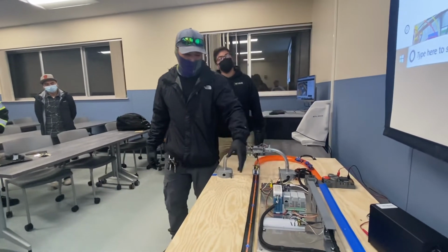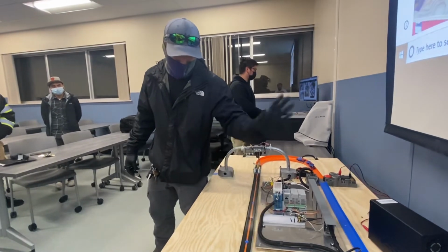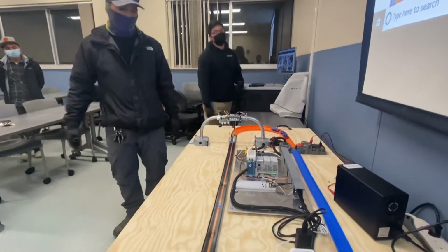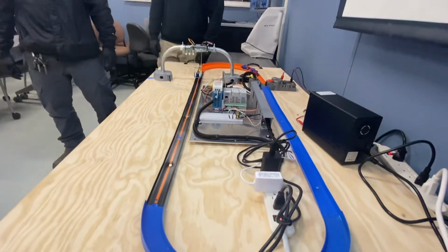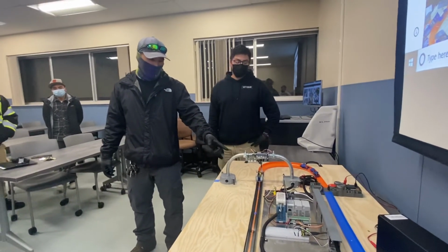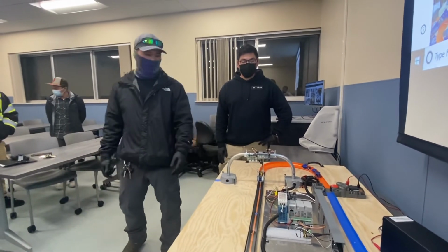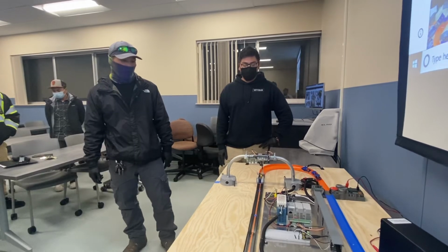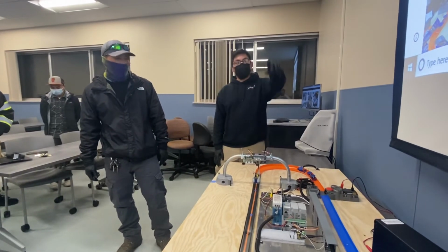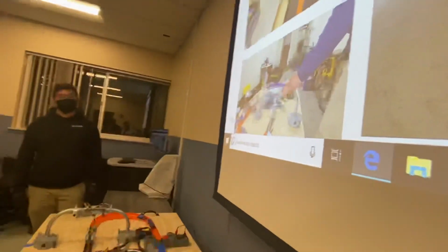as well. Especially with this one, we didn't want any power getting cut and severed and making contact with any other metal parts and causing any electrical hazards for us. Luckily, for the most part, most of it's low voltage. We're running our system off of 5 volts. The highest voltage is only the PLC and the power supply. So yeah, that's what it looked like without the Panduit. It basically was a bird's nest before we cleaned everything up.